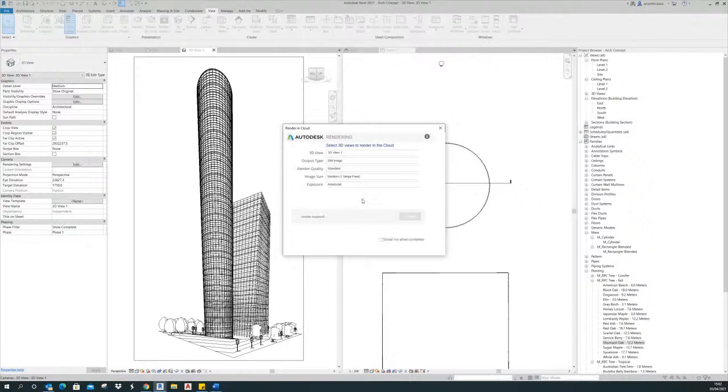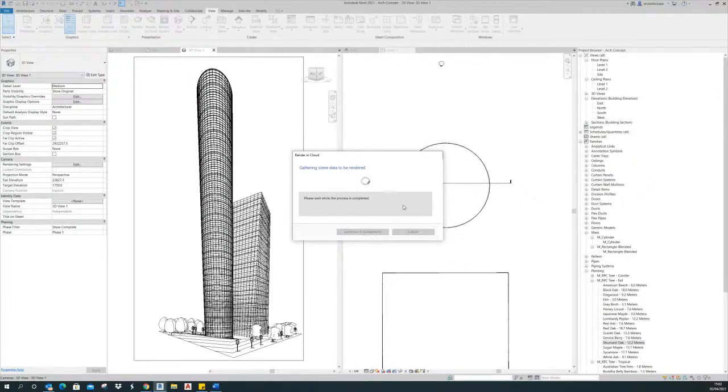And it is very simple. If you want to have this 2D view, the output would be a still image only. Just bear in mind you can do a panoramic view, even a stereo panorama. Find that out for yourself. And for render quality, you just make it final, and image size is 2.25 megapixel. That's two credits, that's okay. And click render. Let's see how fast it could render. I'm not sure if I've set up the background, but let's see what happens.